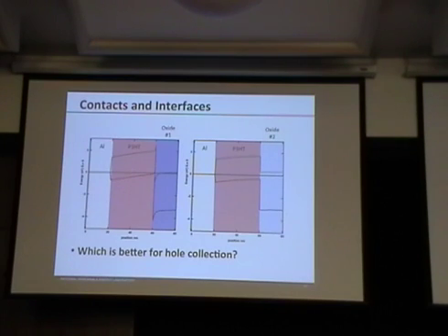Well, given what we talked about yesterday, I went and did this last night. This is for moly oxide with most of the parameters coming from Antoine Kahn's work. And this is zinc oxide based upon some of the stuff that AJ's done and we've done at NREL to characterize some of our systems. Now, to be fair, if we drew in the acceptor, we'd have another electronic level, but it wouldn't really change this picture, because I haven't worried about any of the details in here. I've just looked at what the band offsets are. Very simple calculation, and I've given it some typical carrier concentration.